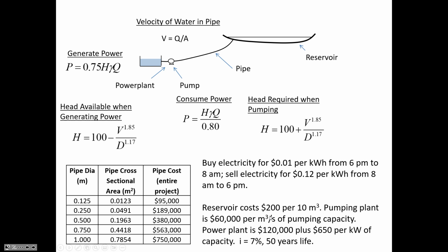Yeah, so let's just assume that this is a really shallow but wide reservoir up at the top so that the elevation of the water surface doesn't affect our head. So we don't have to worry. The head is only influenced by the rate that we're pumping and the head loss due to pipe friction. Okay. That clears it up. It's a good question.